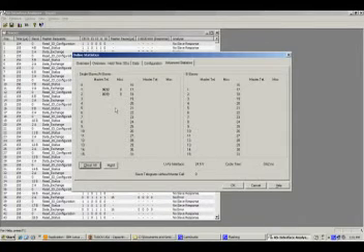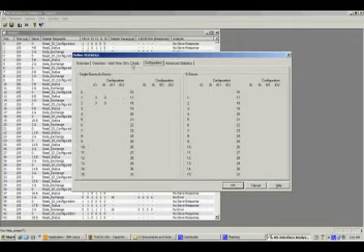Once again, if I loosen my overall cable connector to my ASI network here, you'll see that I can generate missed packets here to the two particular nodes. And it goes ahead and tracks along and so forth. So this is doing the online statistics of my network.